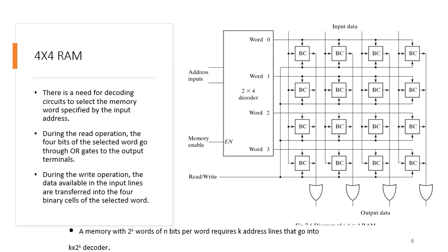Basically this circuit needs a decoding mechanism in order to map those address lines onto the location that we want to select. So we are using a 2 to 4 line decoder. According to the address, 4 basic cells will be selected at that particular time instant. The outputs of this decoder are D0, D1, D2 and D3. Depending upon the address, that particular output is high, and the outputs of the decoder are connected to the select lines of the basic cells.